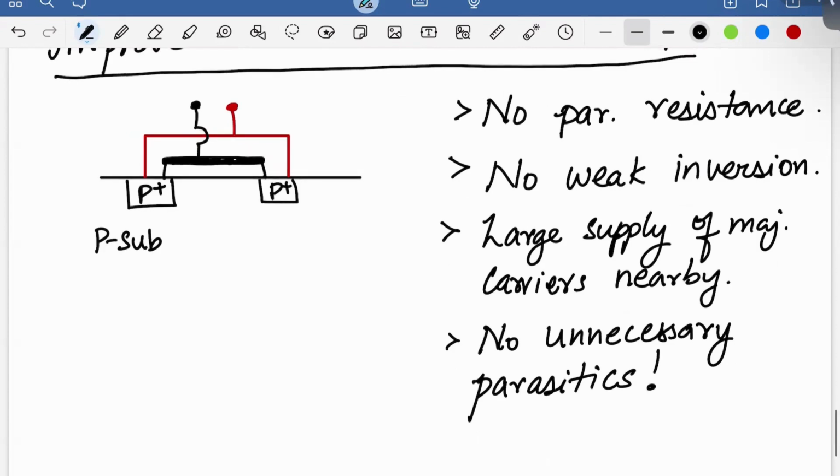The downside, of course, is that such a varactor doesn't always exist in a PDK. We'll see in the GPDK, there is no such varactor. So if you're using a PDK that doesn't have something like this, then you need to custom layout your own device, which of course you don't have a model for unless you do some physics simulations, but you have to do a custom layout and then fabricate it, test it, see if it's working, characterize it. So you may have to go through a couple of runs to do that, right? So it requires custom layout and characterization.